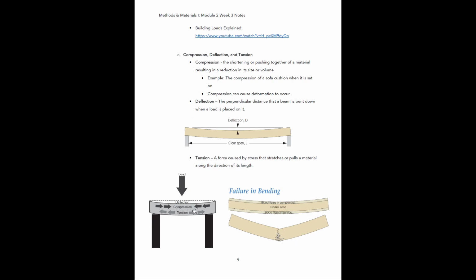It's going to bend the beam downward to some degree. If you look at this line right here, think of that as the beam with no pressure applied to it. Then we apply pressure, and it bends down and bows slightly. The distance between the original top point of the beam and the new location of the top of the beam is your deflection measurement.